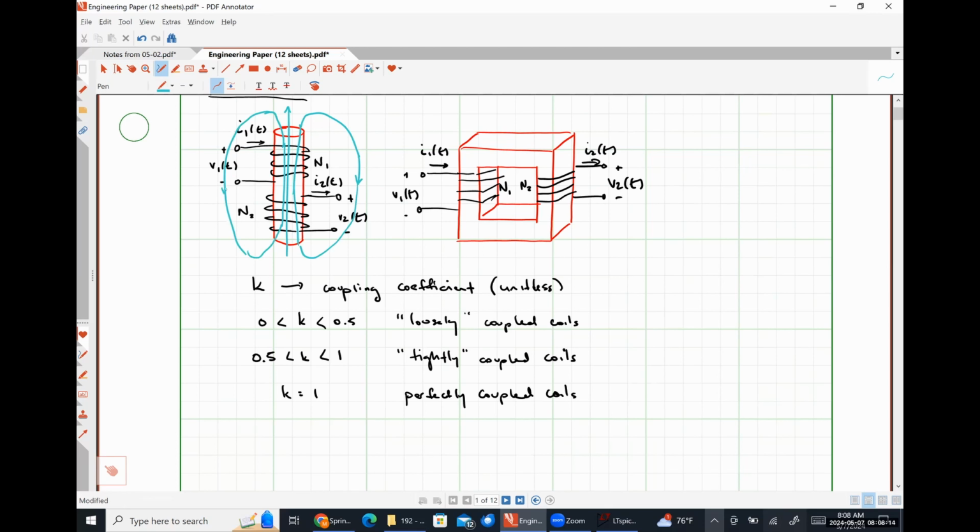And the presence of that air gap gives our magnetic flux place to spread and effectively to lose energy. So those coils are going to have a significant amount of losses. And it also depends on what the core material is made of. So from a purely geometric standpoint, this one's typically going to have a lower k.